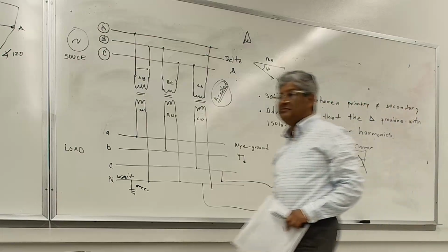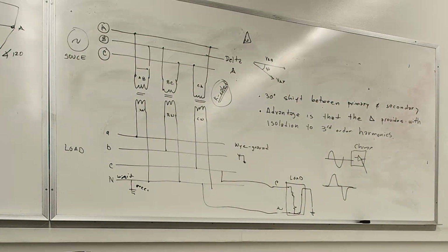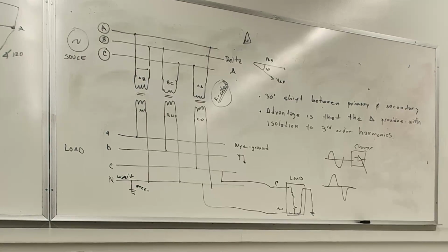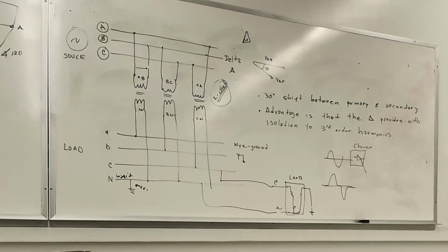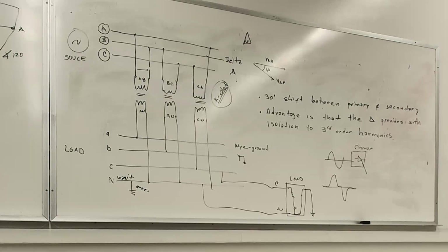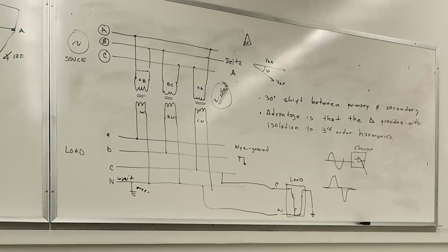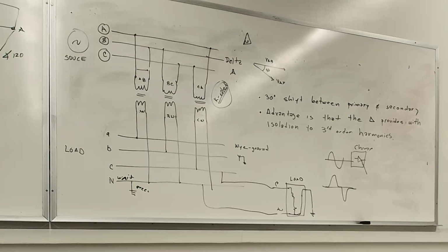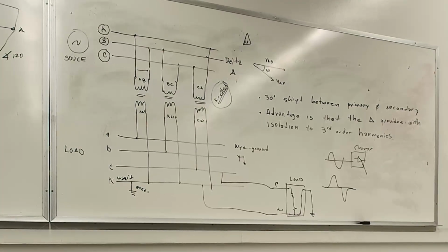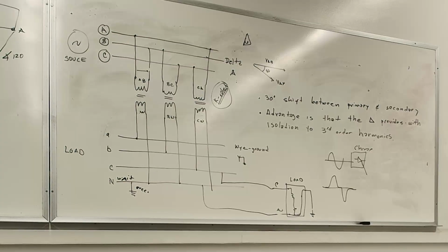So in reality, or in real life, the power plant would have a delta winding, and it goes to the transmission line as Y ground. Say that again. From the source, which is the power plant, it starts with a delta. And then immediately when you go to transmission, you just convert it into Y ground all the way to your